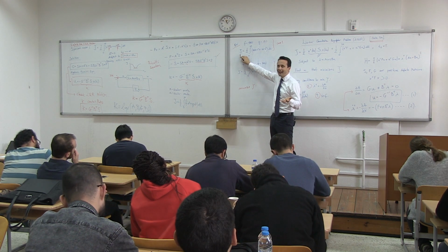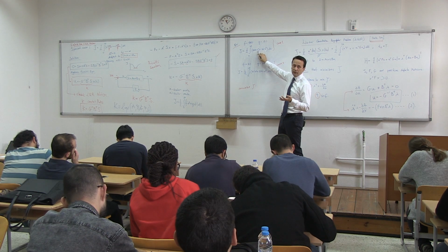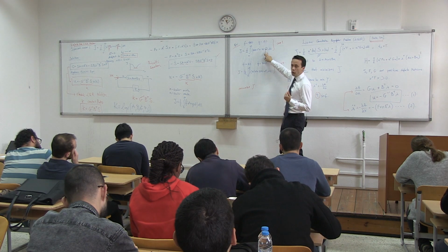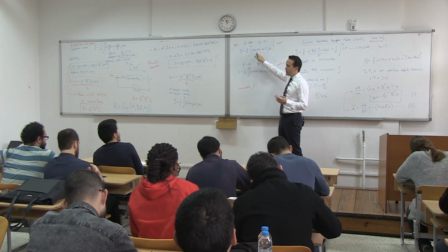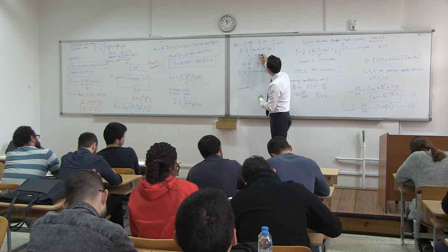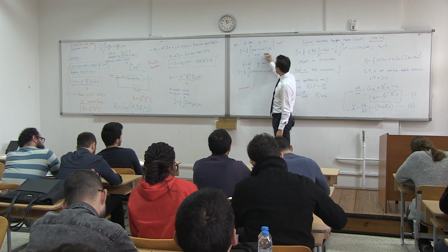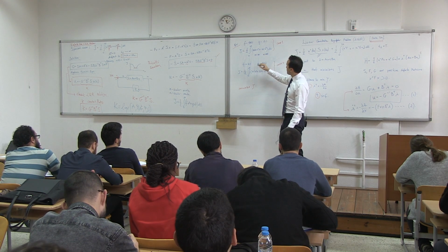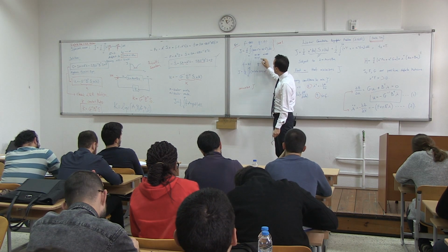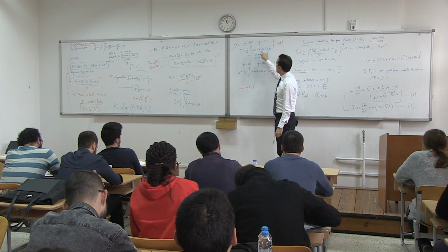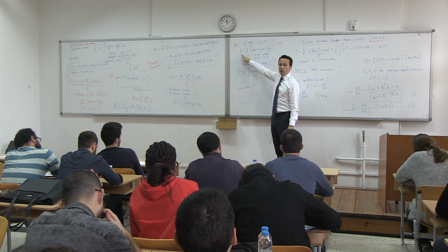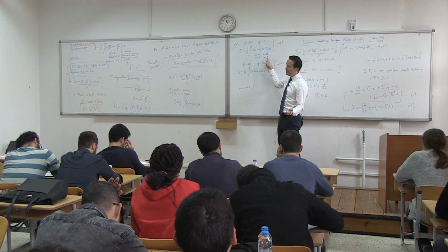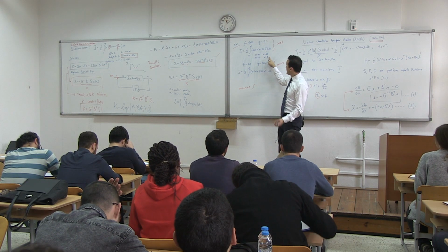Understand that? If you want to minimize J, it's more important what you do with x. So the minimization problem will try to minimize x a lot more than u. Because let's say x is equal to 100, it will be a very large number. If u is equal to 100, it will not be a very large number. So the optimization problem will try to do this probably: x is equal to 0.1 and u is equal to 10. And it will still minimize this J. Because x will become smaller, but it's multiplied with a large number. And u is equal to 10, it doesn't really matter. It's still multiplied with 0.1. So this is a better solution than this.